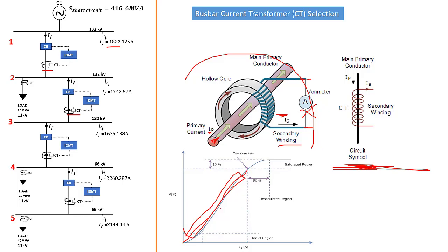We know that the output current, which is IS, is following what the input current is doing. So it's linear. But now when the output current stops following the input current, we reach the saturation region, this region here. So we're no longer in the linear zone or the good zone. We're now in the danger zone.